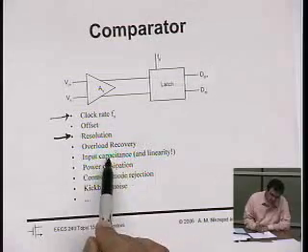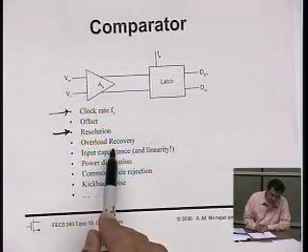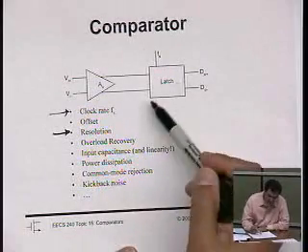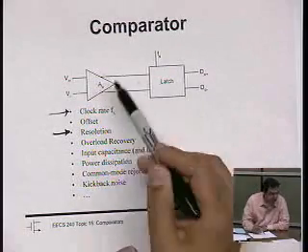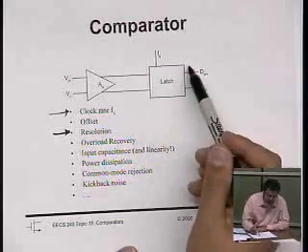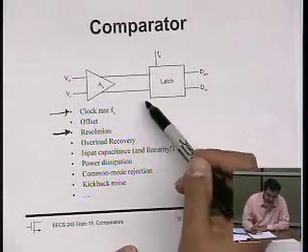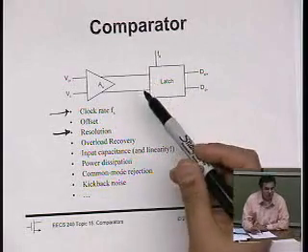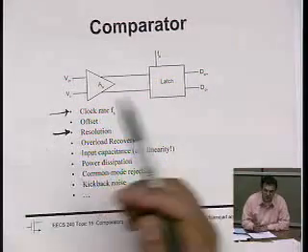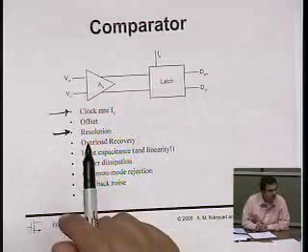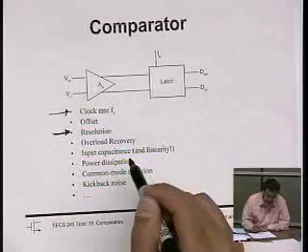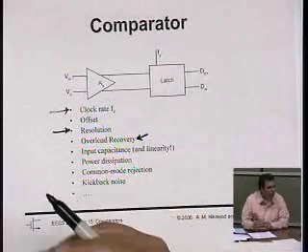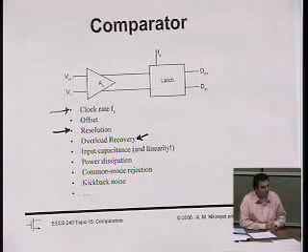One is overload recovery. So if I'm designing this circuit and I want to clock it fast, I may find that if I have internal stages in this latch that clamp to VDD or ground, it's going to take me a long time to unclamp the circuit, because unclamping means discharging capacitors, and that's determined by slew rates, right? And so if I don't want to dissipate too much power, then I'm going to have to do something to avoid internal nodes of the circuits clamping too much.